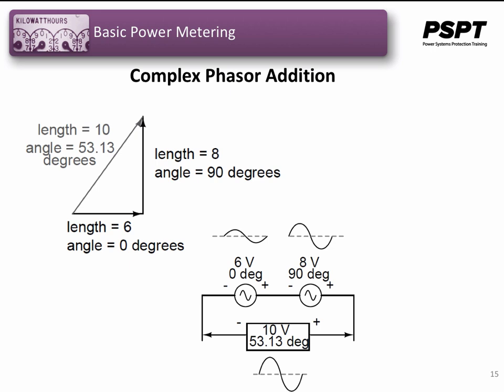Note that it is possible to obtain voltmeter indications of 6 and 8 volts respectively across two AC voltage sources, yet only read 10 volts for total voltage. With AC, two voltages can be aiding or opposing one another in any degree between fully aiding and fully opposing inclusive. Without the use of phasors, that is, complex numbers notation, to describe AC quantities, it would be very difficult to perform mathematical calculations for AC circuit analysis.